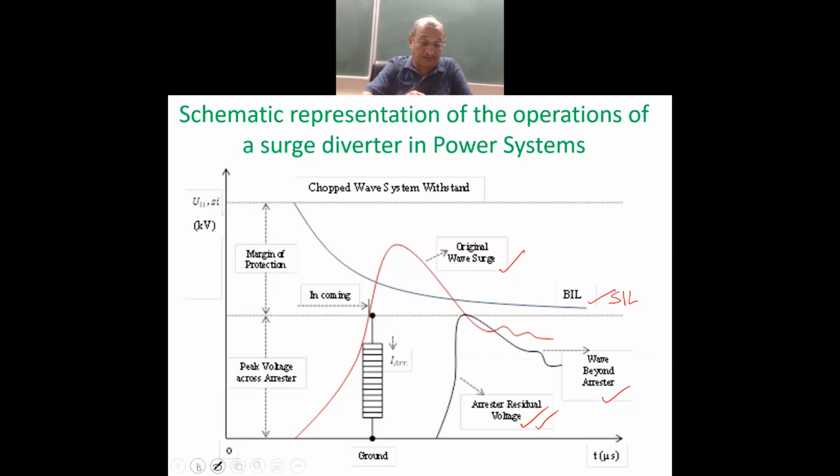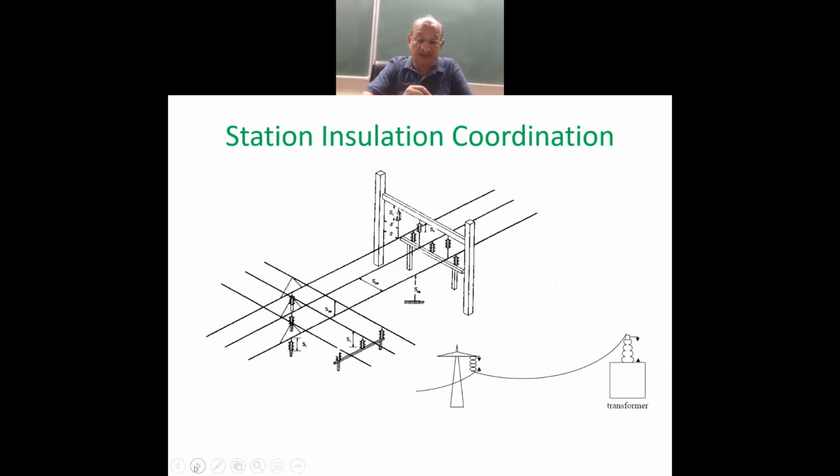So this is a simple substation, just a schematic drawn for the three-phase lines, showing how they are connected. They are connected over the insulators from the poles. The high voltage conductors are supported by the insulators, and insulators are provided with the rod gap or the horn gap.